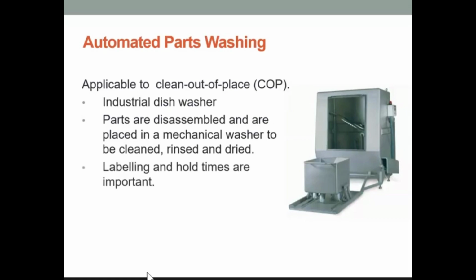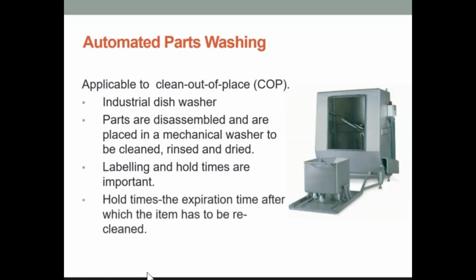Labelling and hold times are really important here, as in everywhere else. You need to label all of your pieces of equipment so they don't get mixed up or put into the wrong process in error. You need to have your dates on them so that you can follow your hold times, so you know what's clean and within its hold time. Hold times are the expiration time after which the item would need to be re-cleaned.